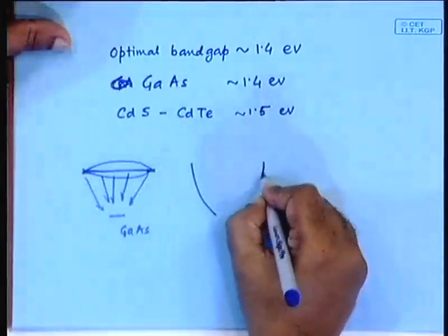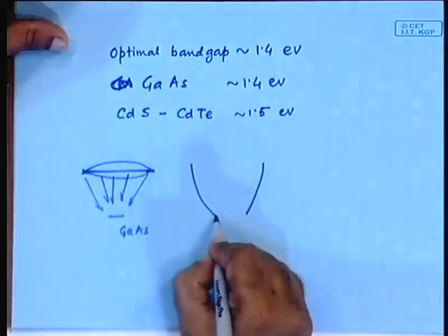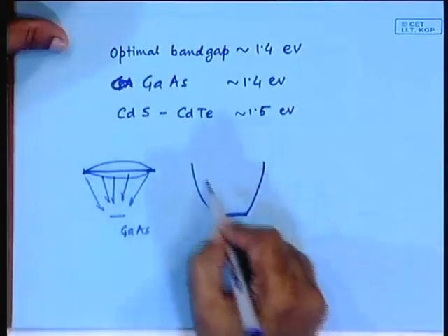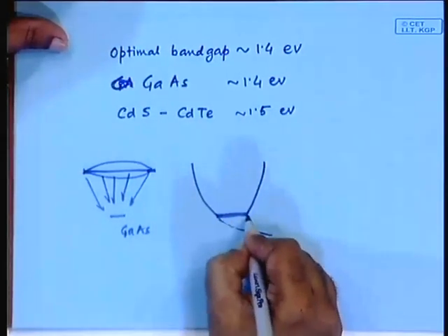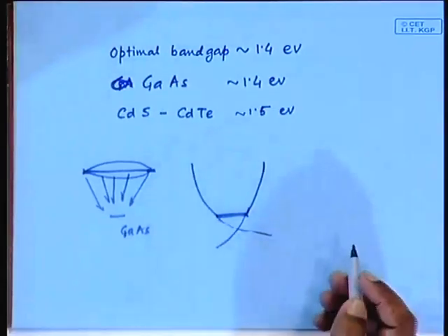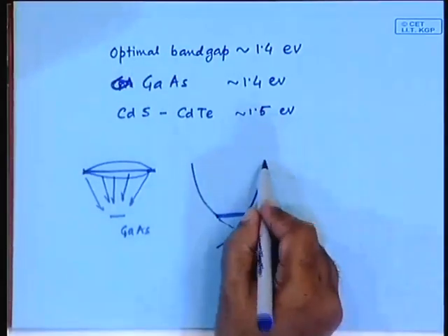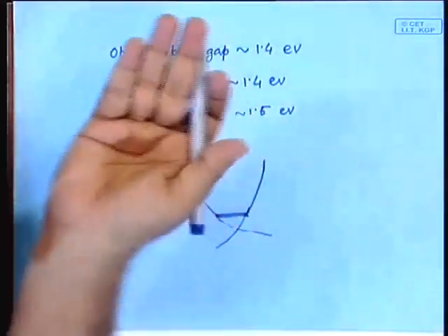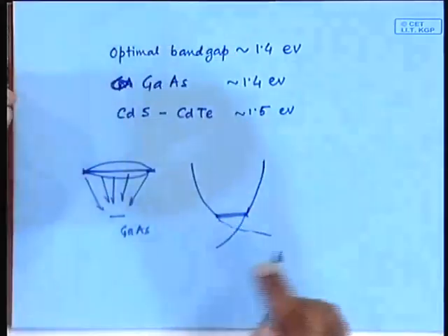The other type of concentrator that is considered is the reflecting concentrator, and you have learned what kind of reflecting concentrators. For example, the Winston's profile, where you have... and here is the gallium arsenide solar cell. These are two parabolas, and this parabola has this as a focus and that parabola has that as a focus. That is the construction. So, you can have some kind of aluminum reflecting bowl, and on the bottom of it you have the gallium arsenide solar cell.